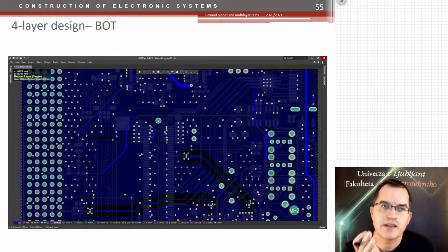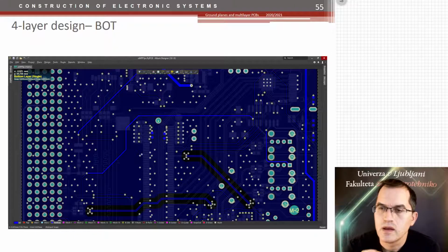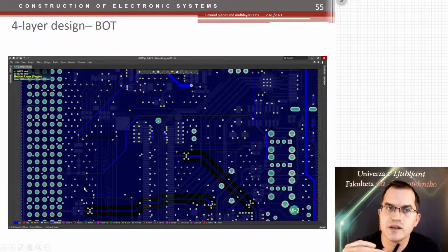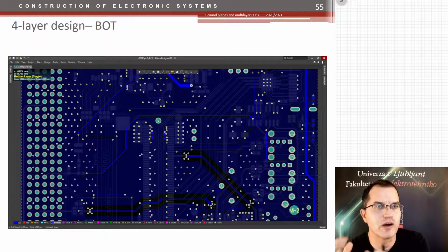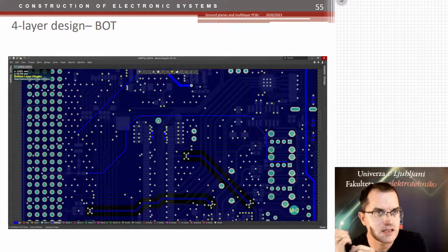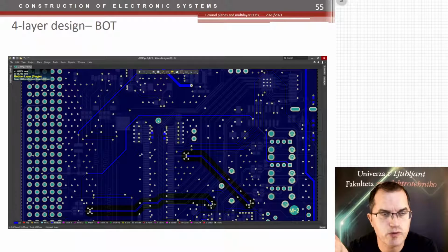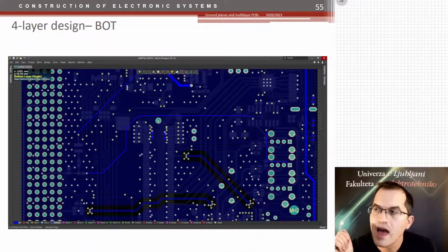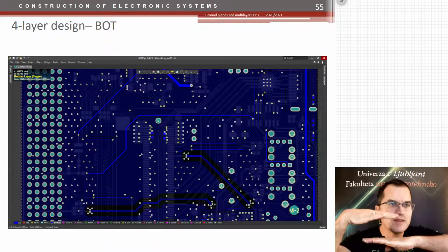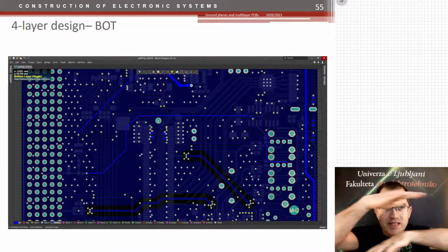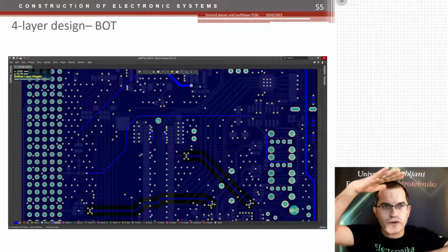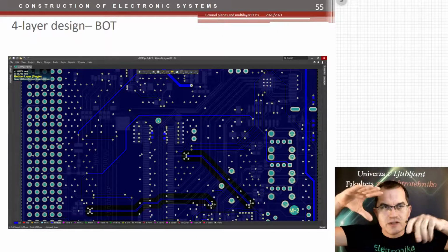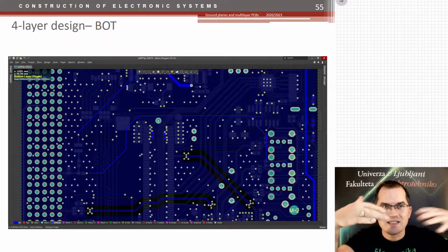That's good in several ways. First of all, with a lot of ground planes and connecting them to each other, you make a really nice and firm ground plane that has the lowest possible impedance, which of course decreases the common mode interference problems. And you make even PCBs. All the layers of the PCB are covered with copper, so your thickness is even, and also there is no bending because of no asymmetrical issues.